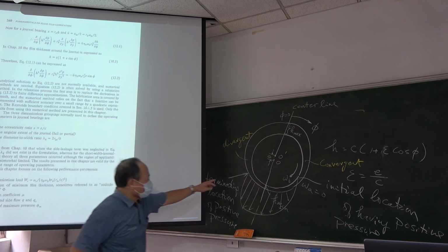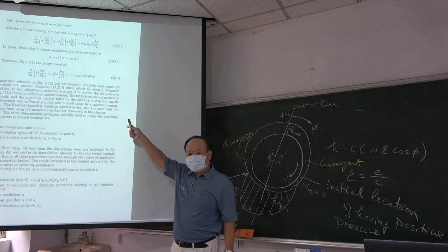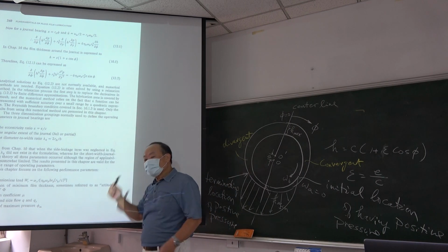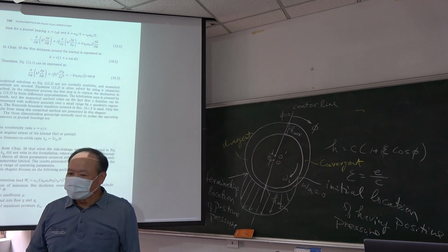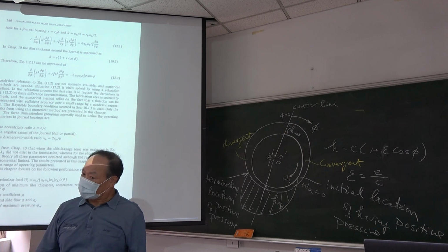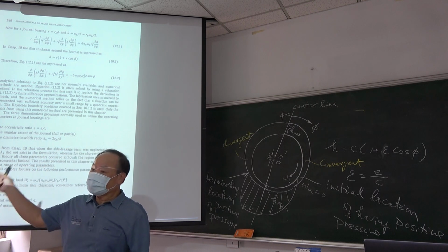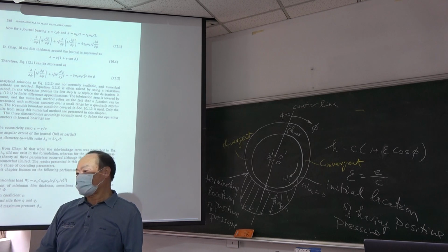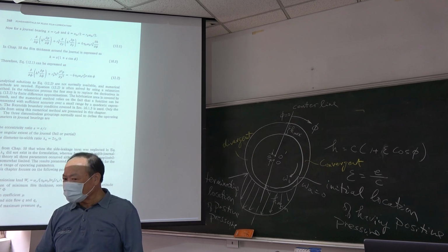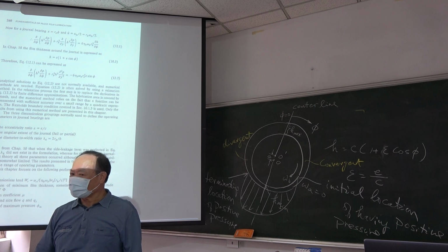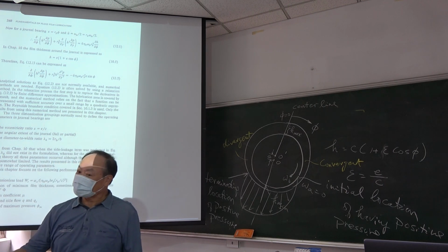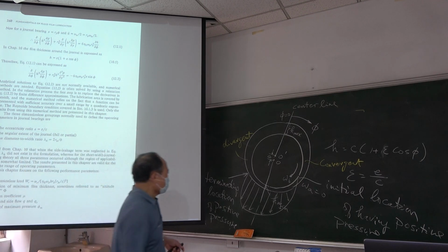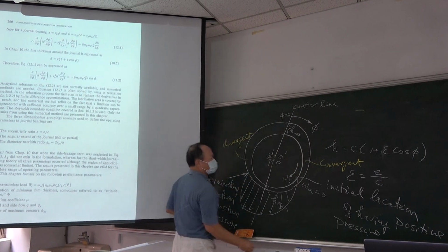If we use the numerical method to solve it, we strongly suggest you use the Reynolds boundary condition because it can be solved without any difficulty, and you can also obtain a high precision solution.